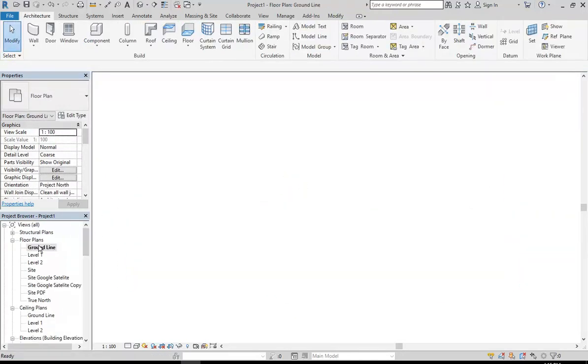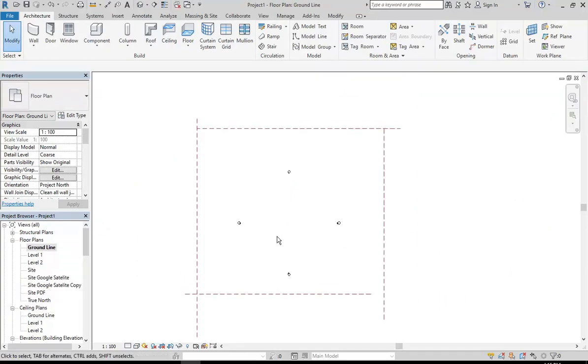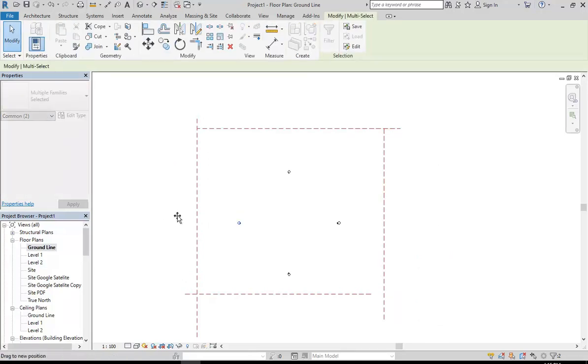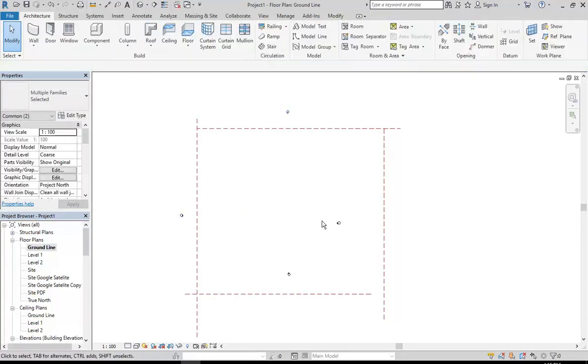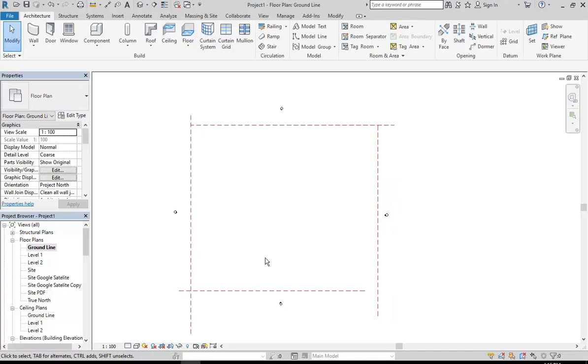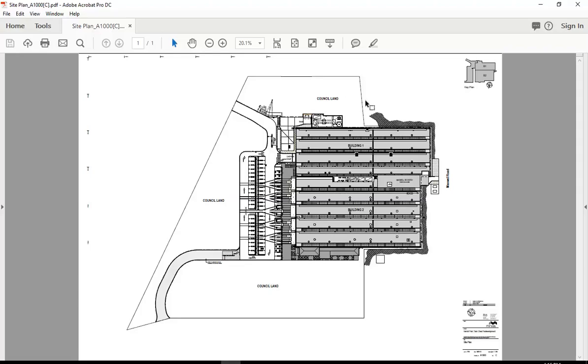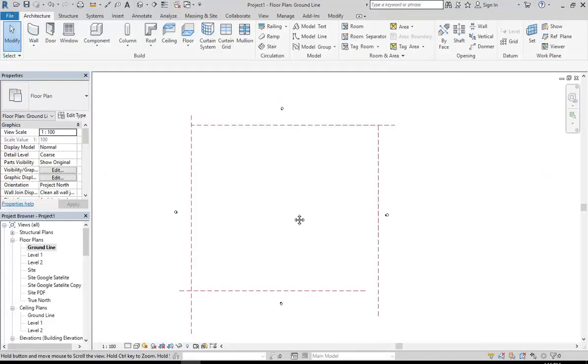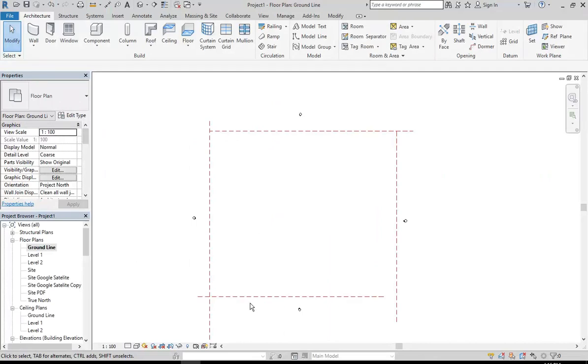And then going one step further, even the elevations. So we know how big the building is with those reference planes, and now we can get those elevations and bring them outside here. Notice I'm selecting them with a window because there are two parts to the elevation. Over here you can see the two in brackets. So I just want to bring the whole group together. And then you can of course start drawing all the walls, and you can repeat the process to insert the other floor plans. I won't show you that.